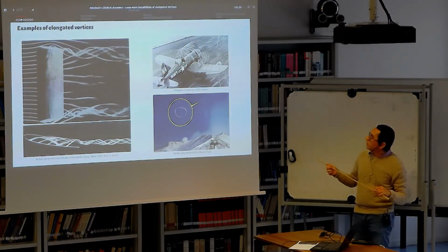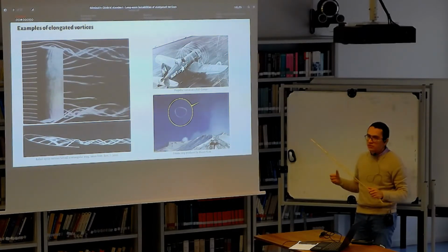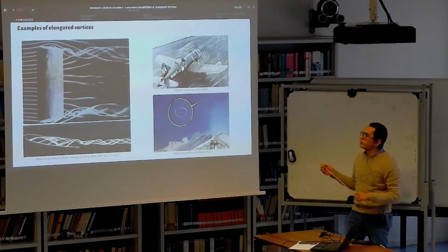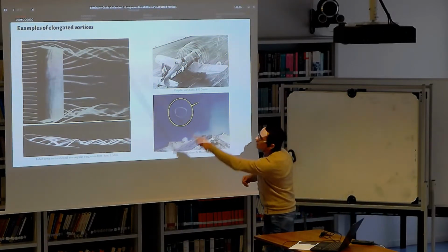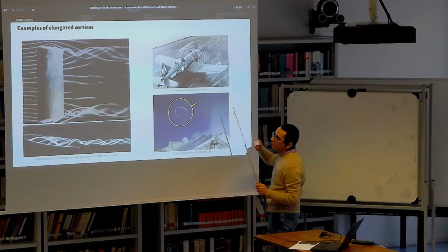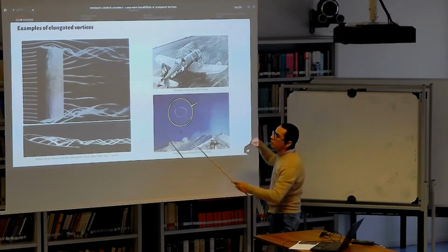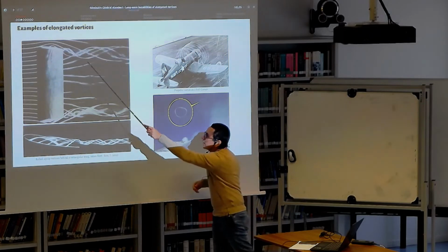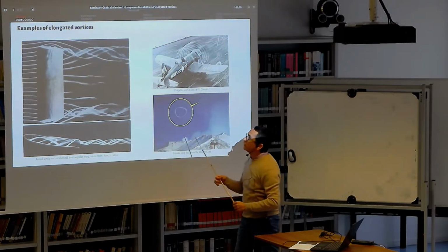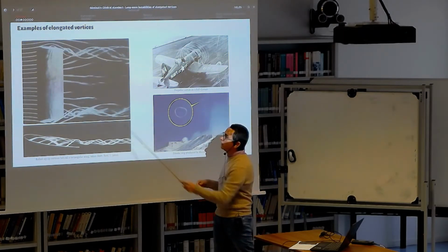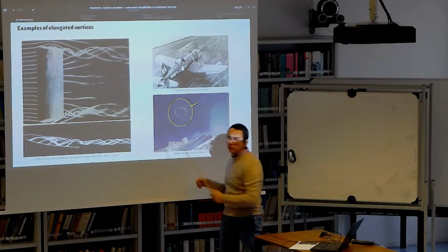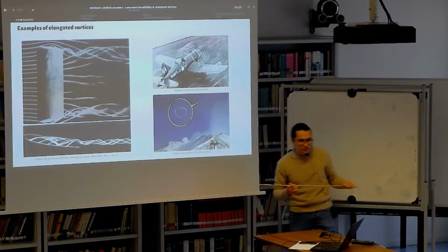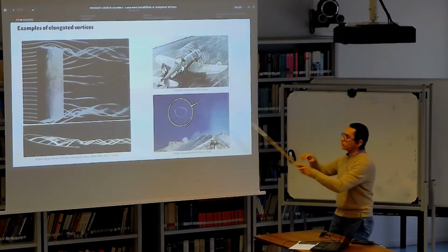And we also have the vortices that are detached from a wing profile, like it's shown here. So you have this wing profile with some incoming flow, and depending on the operating conditions, you have some vorticity that detaches all along the profile that is going to roll up near the edges and create these concentrated tip vortices, which are advected downstream.